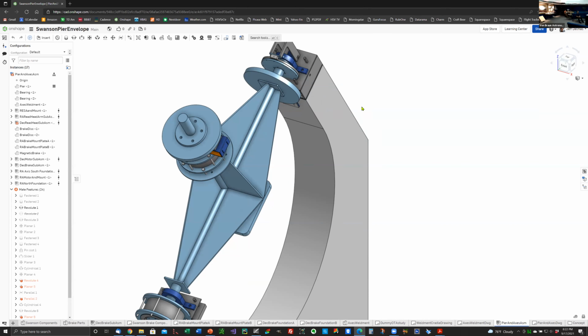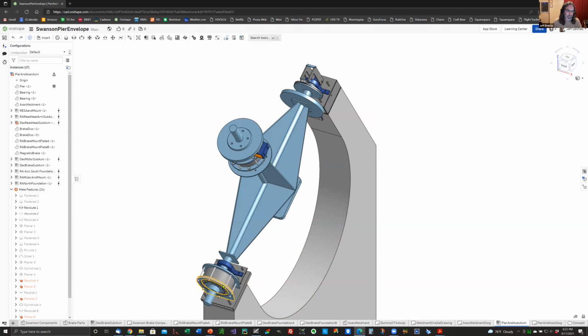I was wondering if you could explain how a direct drive system works. So all direct drive means is that the motor drives the axis directly and not through a gear system. Anytime you've got a gear system, you're going to introduce errors of various sorts. You're going to have slop in the gears, the teeth will not mesh perfectly, and there will be a little back and forth because of that.